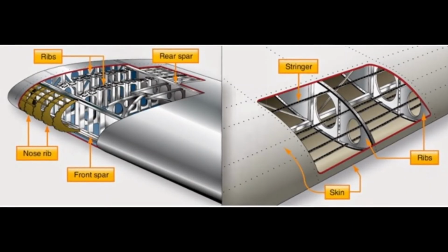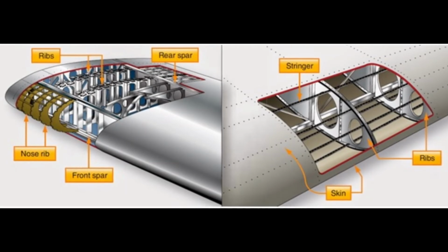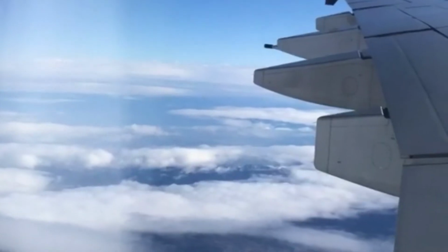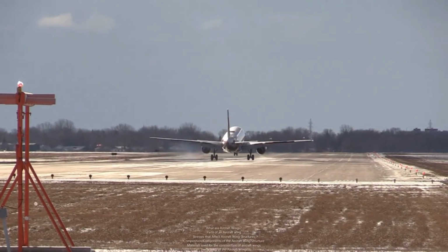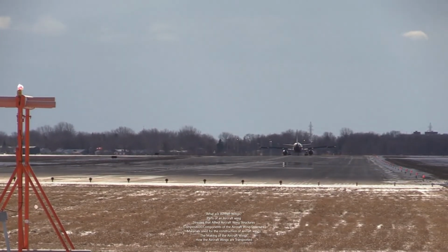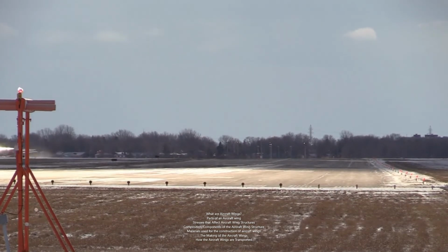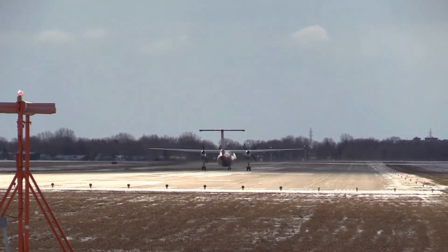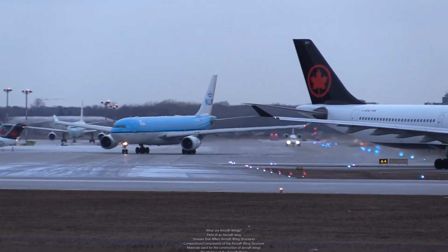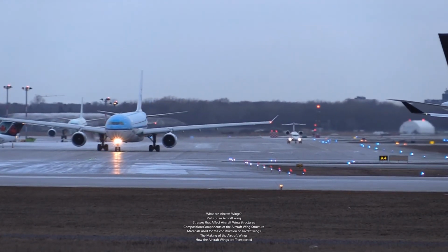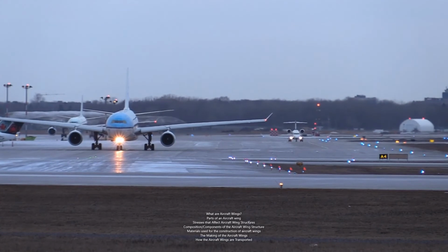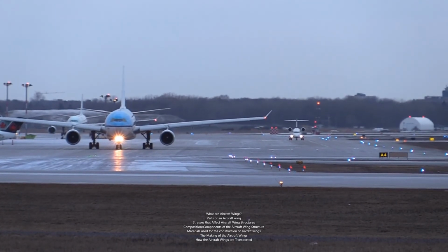Holes are drilled very carefully so that their diameters can be accurate and their axes can be normal, perpendicular, to the skin. Some regions of the wing that are highly stressed have their holes manually reamed out. The rivets must completely fill out the holes they are put in and also create compressive stresses in the material surrounding it. Thus, precise calculations and installments are made. The size of the fasteners and thickness of the skin is also carefully selected by structural engineers to ensure they are able to withstand the stresses they are expected to bear.